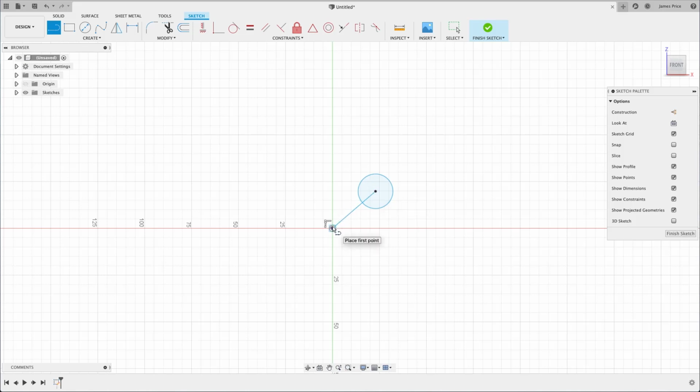For instance, here I am attempting to create a surrounding box using the line command, although I've missed placing the last point with the first. I can simply click on one vertex and snap it to another, creating that constraint and profile as indicated by the light blue shading. We can now extrude this to a 3D shape.